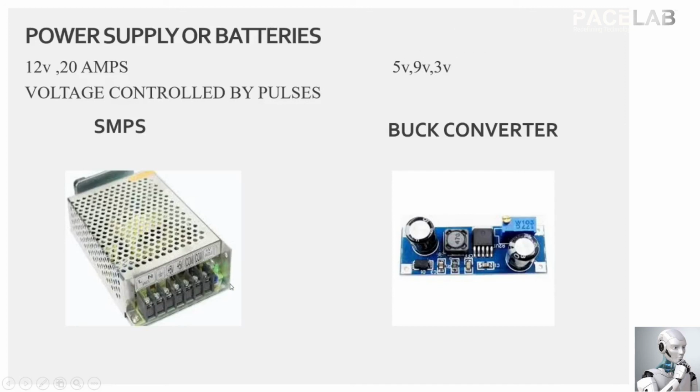One thing you should note is that there will be a switch available in the SMPS which has 2 options: one is the 110 American standard and the other is the 220 Indian standard. So be sure that the switch is in the 220 position.